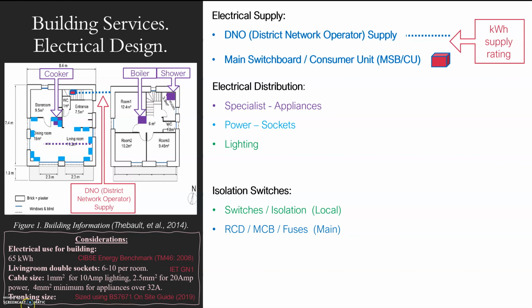And down here I've actually got a guidance from the IET guidance note, so it's saying that actually we could design 6 to 10 per room. That's normally the same per circuit as well. And then finally, lighting. We've got 3 ceiling pendants here for our lighting.